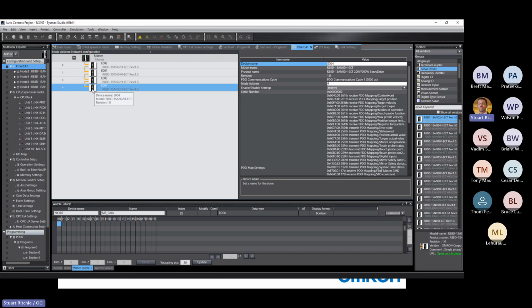Then the very last device flips that packet around and sends it back, and on its way back, the devices deposit their outbound data for the master into that packet, and it all arrives at once. So very efficient, very good for device level stuff. We're not sending megabytes of data over the EtherCAT network. It is limited in size, but very fast, very efficient.